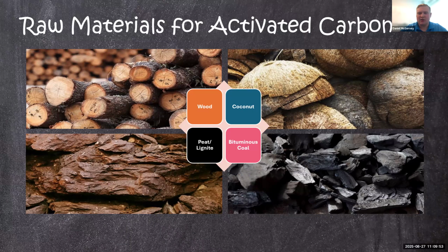The coconut carbon is really the opposite problem. There's actually a lot of parking lots. There's a lot of parking space in adsorption sites, but there's not a lot of transport pores or highways. So you can think of this as like a traffic jam happening in a city where contaminants are basically getting stuck, not being able to actually get to the parking lots or get to the adsorption sites, even though there is plenty of room once they get there.